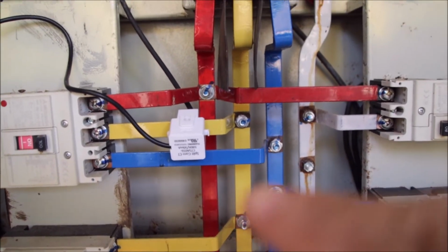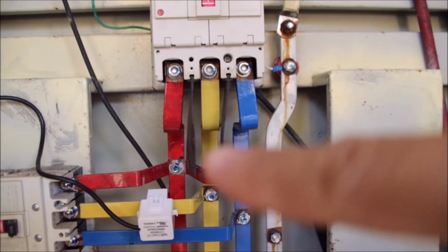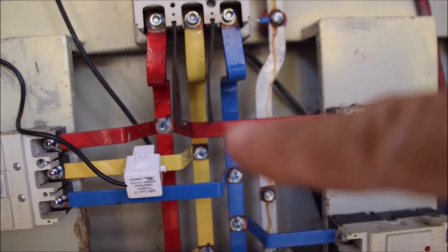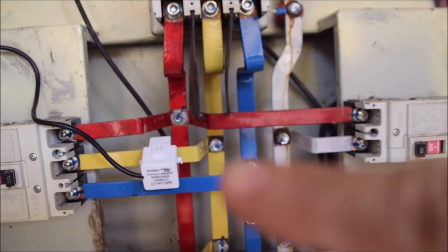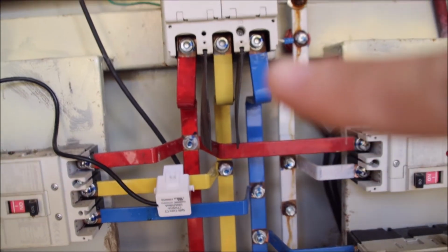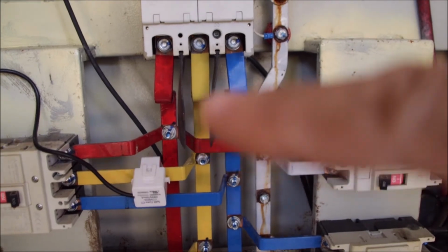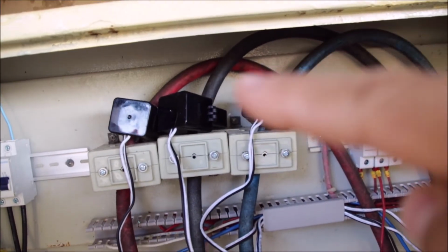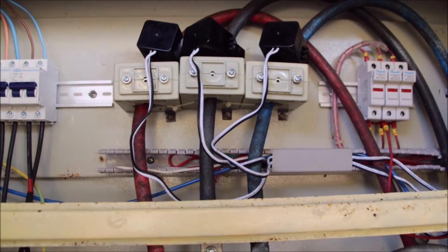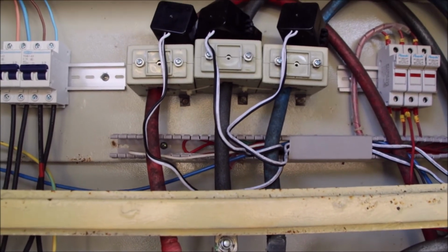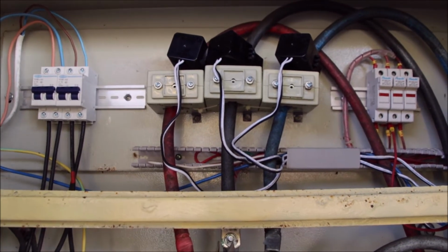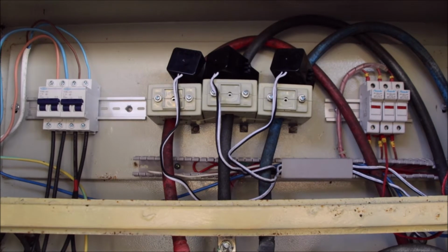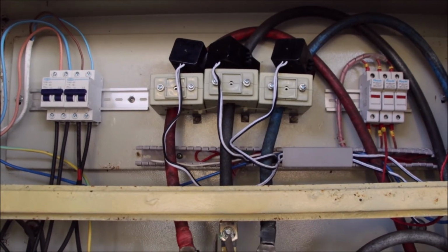So I need to connect now the CT somewhere upstreams here. But here, this main bus bar here is an 18mm bus bar. So I cannot use this CT anymore. It is not big enough from the hole. But that place actually is not very good accessible, so actually I want to connect the CT somewhere here on the incoming main cable, same place as the CTs from the smart meter. But for that, as I said, we need a new CT, and I will show you how to get one and what you have to basically take care of.